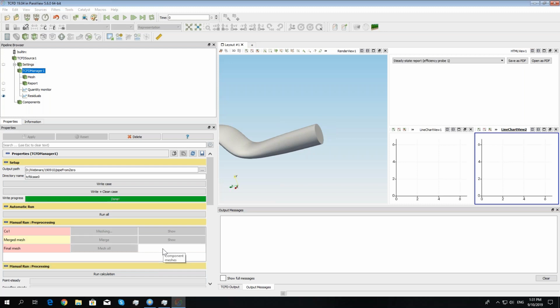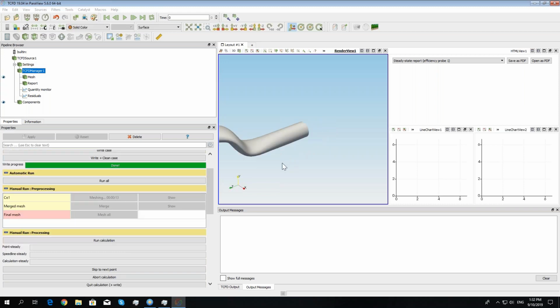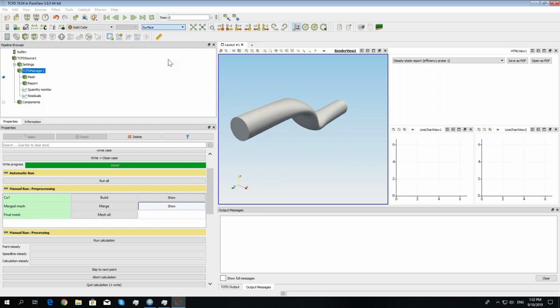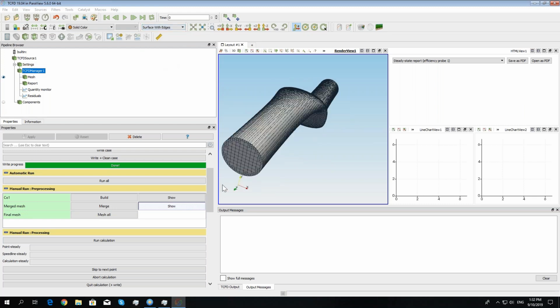Let's mesh it all. Based on my setup, behind the scenes it creates all necessary files and runs all necessary applications of OpenFOAM, and at the end we will see our generated mesh, and that's all. There is no need to provide snappyHexMeshDict files and other helpful files for additional applications. So my mesh is generated now, so I can close this, and this is my mesh.